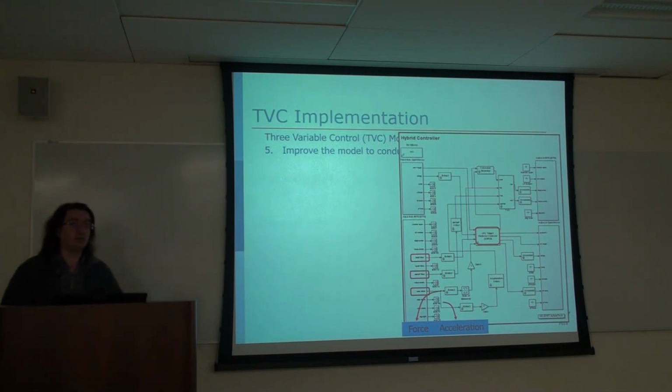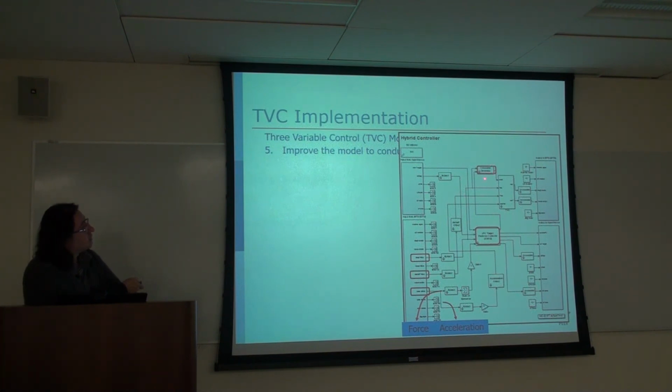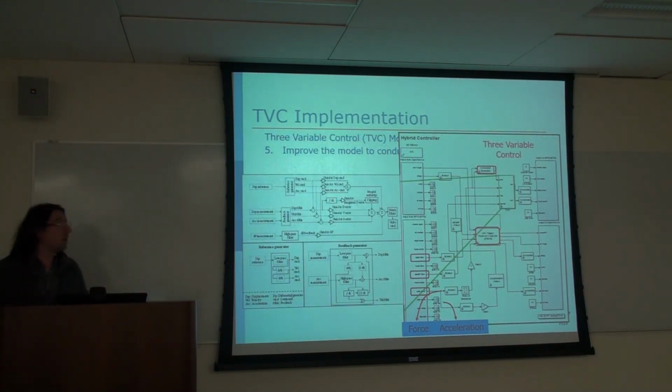Different from the ground motion case where we have the displacements already ready, we get the displacement commands as the outcome of this predictor corrector box. Then they go to the command generator, and they are offset. Then all these inputs eventually go to the three variable control, which is the same as in the previous ground motion case. So this becomes our Simulink model to run a hybrid simulation with the predictor corrector using the three variable control.